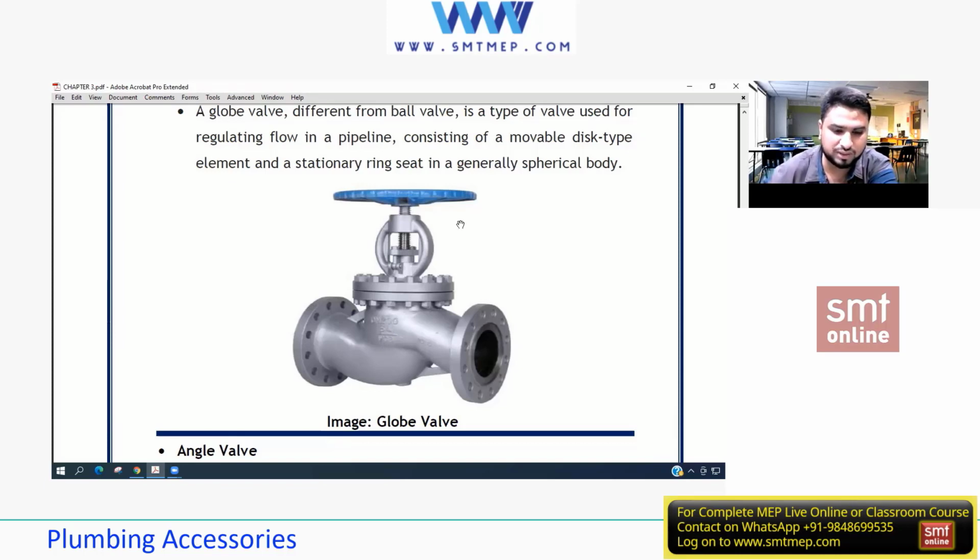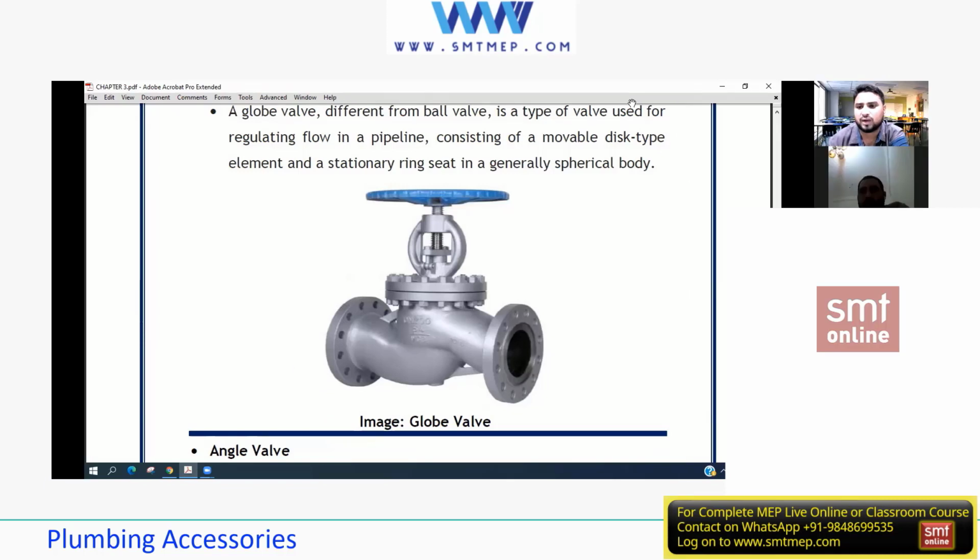And if you remember, they check on the other side how much pressure is required. For example, they were generating electricity. So as per the pressure required in the line, I can adjust. That's a regulating valve, isn't it? So this is used for the higher or bigger flows. This is a globe valve over here.